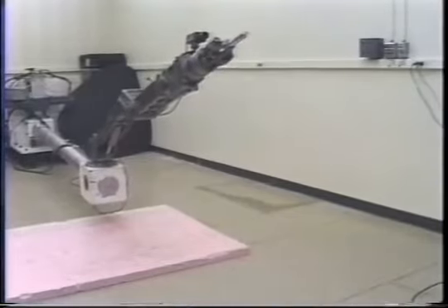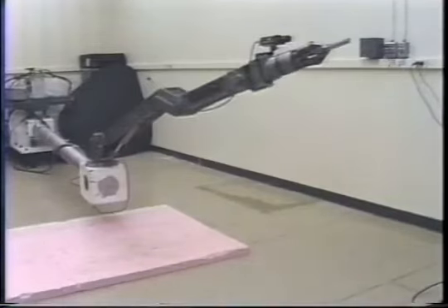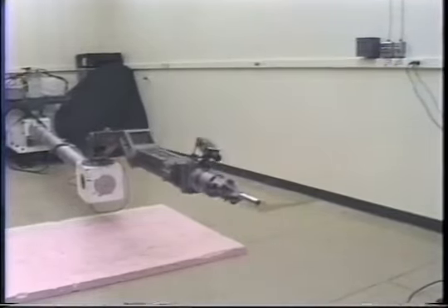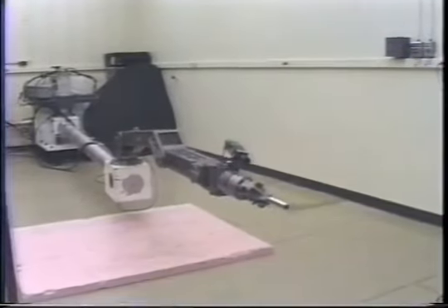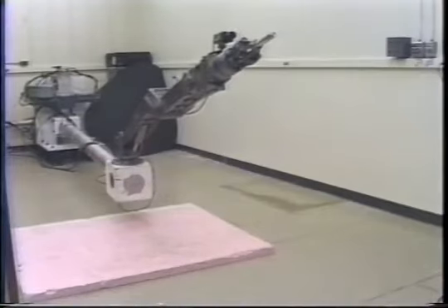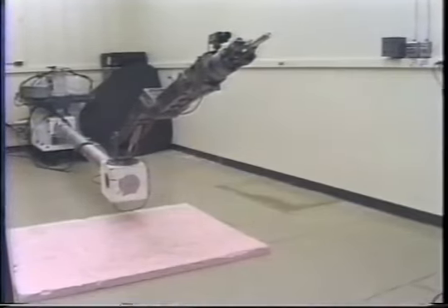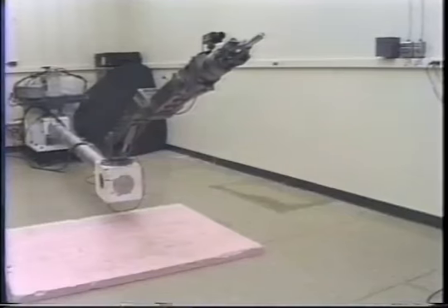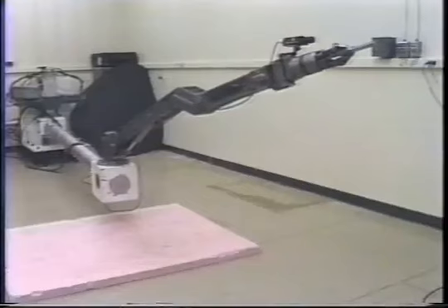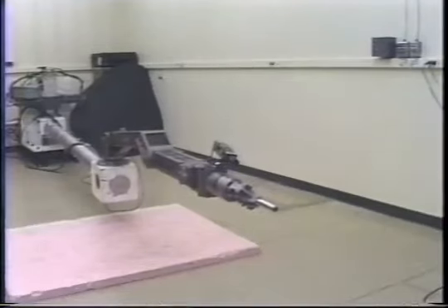The motion of the micro-manipulator with a conventional PD controller can easily excite the macro-manipulator. These structural vibrations can last more than a minute and have detrimental effects on safety and efficiency. However, with inertial force active damping control, the micro-manipulator counteracts the structural vibration using strain gauge feedback at the base while it follows desired positions. Both horizontal and vertical vibration damp out in less than 2 seconds.